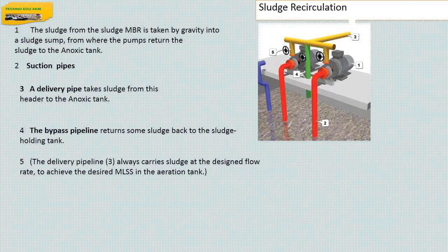Another tank, named the treated water tank, is for collecting treated water. Treated water is pumped through the membrane suction pump and further disinfected through UV to kill the bacteria, and gets collected in the treated water tank. The treated water is disposed of with the help of a hydropneumatic system of capacity 12 cubic meter per hour for irrigation from this tank.